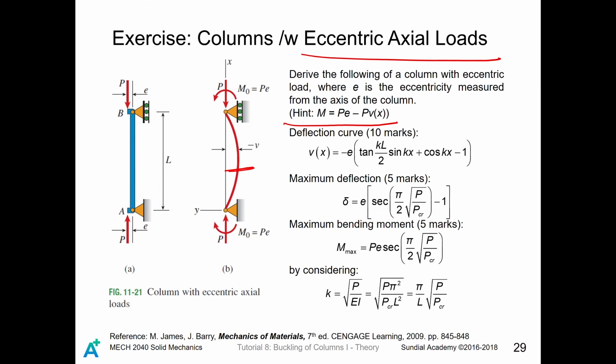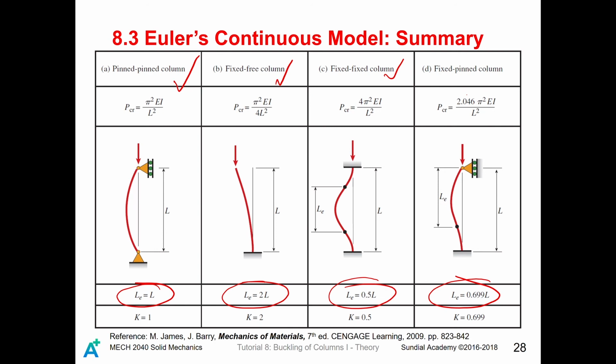so eventually you have three models. Again, to emphasize, you have a simple model, still remember? It consists of two rigid bars linked in the middle by a rotational spring, as well as pinned ends. Okay, and once there is some load applied on it, then there is some critical load, and surprisingly, the theta could be cancelled out. Also, we have Euler's continuous model of four supporting types.